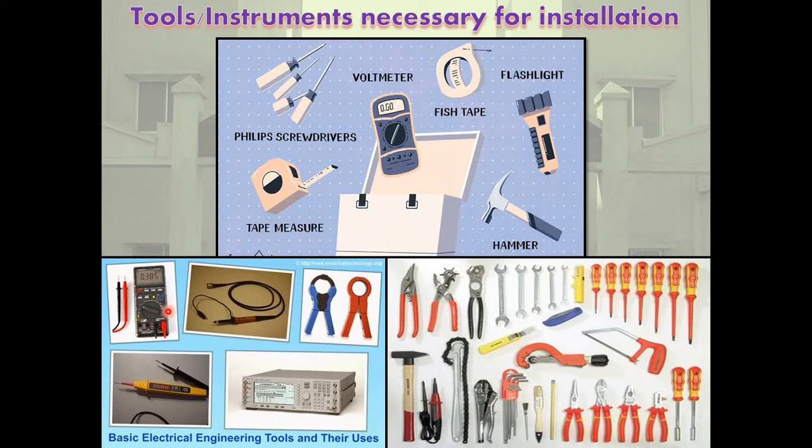Use caution around heat sources. Some panels and equipment get hot while operating. Everyone should be aware of this area and use caution when nearby. PPE like gloves or flame resistant clothing may be required in this area. Be careful when cleaning. When cleaning around a panel or equipment, one should note other possible hazards too, like fire and explosion hazards, need for PPE during cleaning, risk of electric shock.